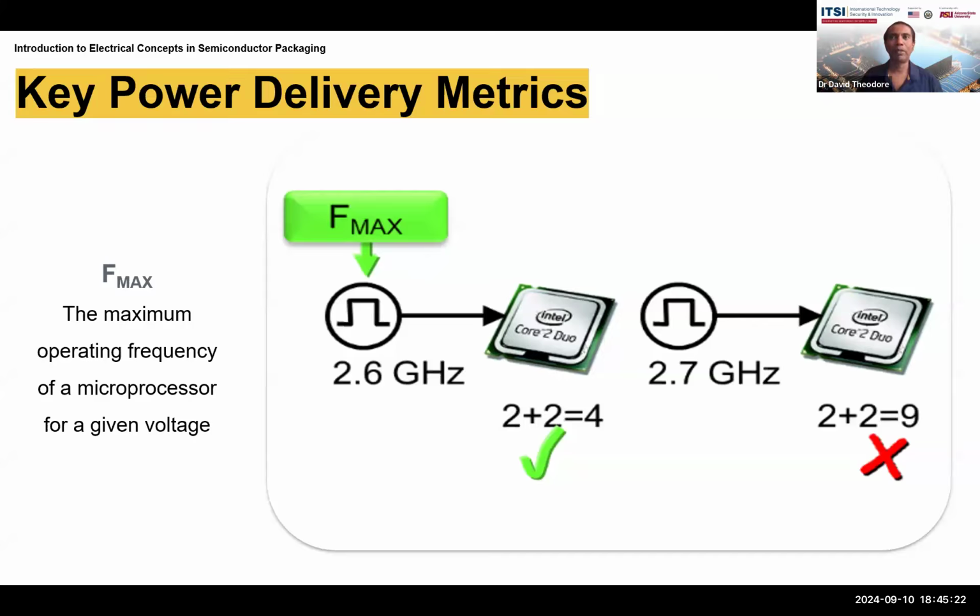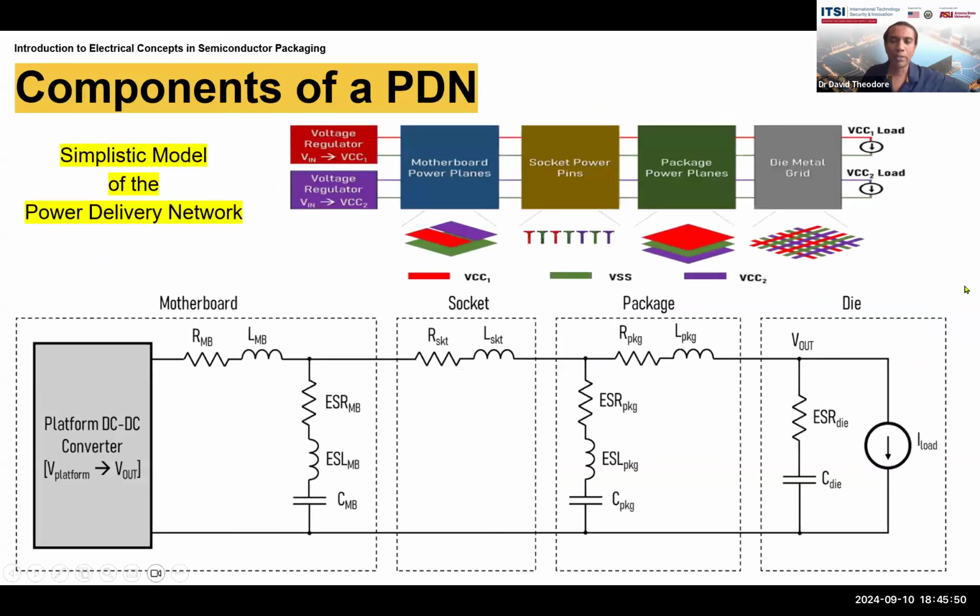One signal, one number one, has not moved past a given device, a given gate, for instance, before the next one comes in. As a result, you can end up with incorrect logic. And so you end up with answers like 2 + 2 = 9, which is wrong, of course. This is one reason why you have to be careful about operating the chip at the designed frequency.